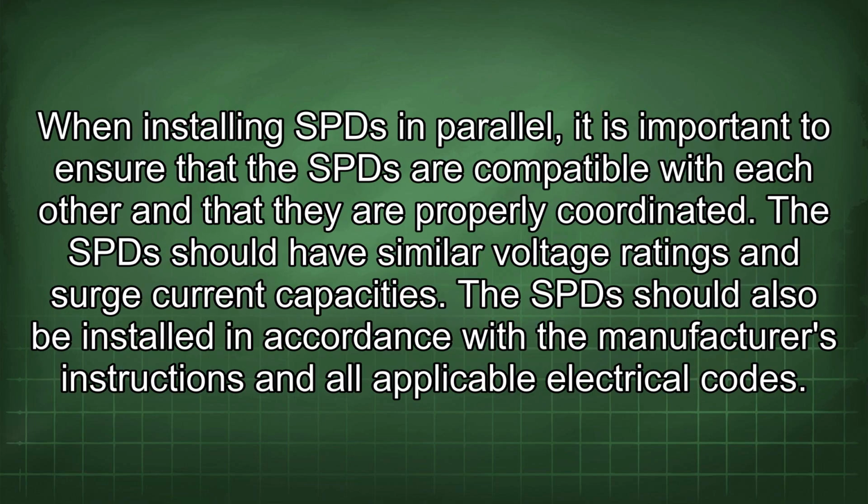When installing SPD in parallel, it is important to ensure that the SPD are compatible with each other and that they are properly coordinated. The SPD should have similar voltage ratings and surge current capacities. The SPD should also be installed in accordance with the manufacturer's instructions and all applicable electrical codes.